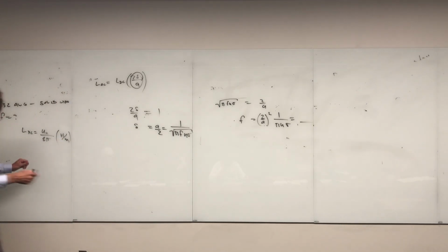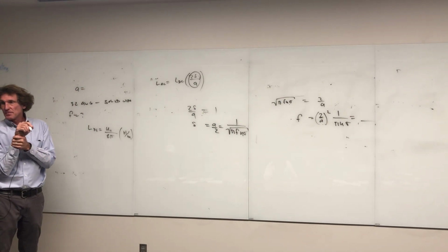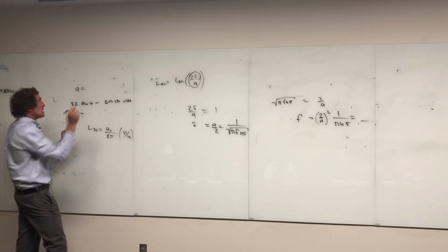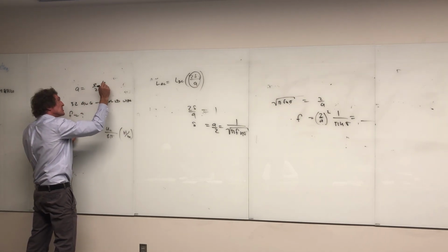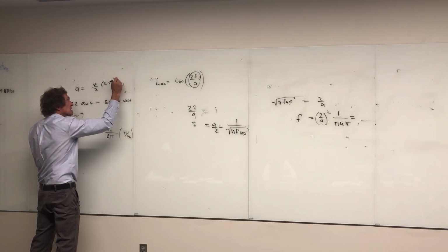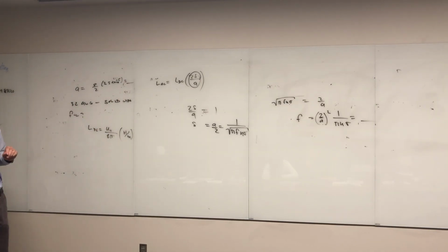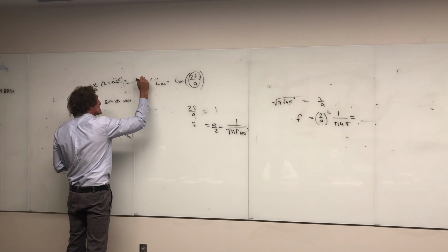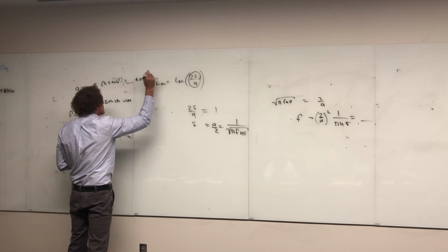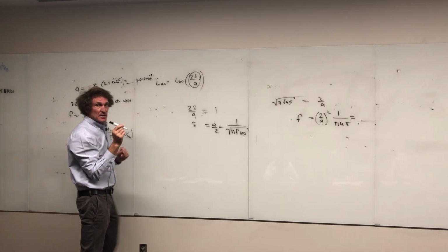All right, so now we've got to find the radius. Can somebody give me what A is for a solid 32 AWG in mils, and then we'll convert it to meters? 8 mils? All right, so it's 8 divided by 2, 4 mils times 2.54 times 10 to the minus 5th, and that would be meters. We got 1.016 times 10 to the minus 4th.